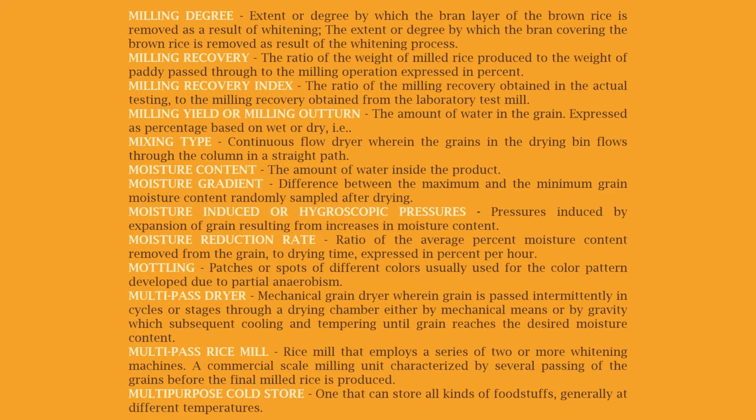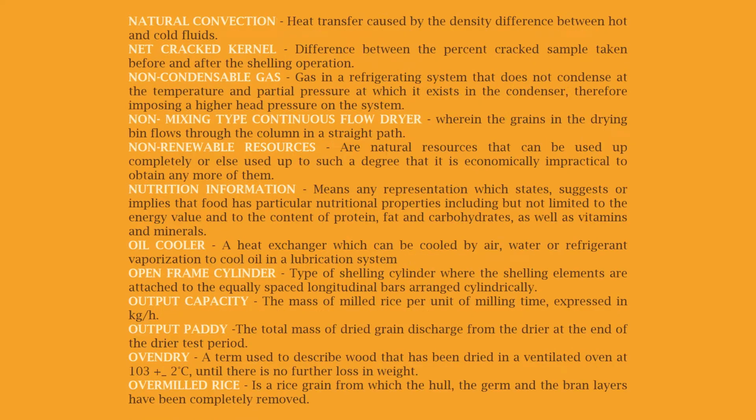Multipurpose cold store, one that can store all kinds of foodstuffs, generally at different temperatures. Natural convection, heat transfer caused by the density difference between hot and cold fluids. Net cracked kernel, difference between the percent cracked sample taken before and after the shelling operation. Non-condensable gas, gas in a refrigerating system that does not condense at the temperature and partial pressure at which it exists in the condenser, therefore imposing a higher head pressure on the system.